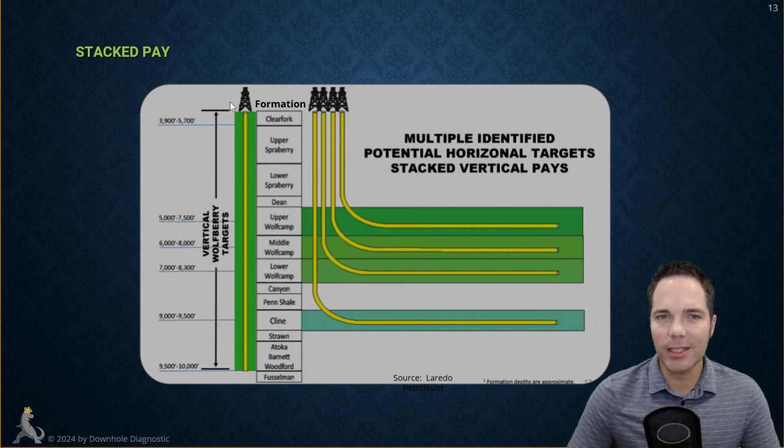All of those characteristics I just described are not the same in a horizontal well. You cannot put the pump intake below the bottom perforation. That would be at the end of the lateral. Typically, you are setting that pump intake right there above the kickoff point, and the kickoff point is where it starts to curve down as it's going down into the horizontal right here. So you would set the pump right here.